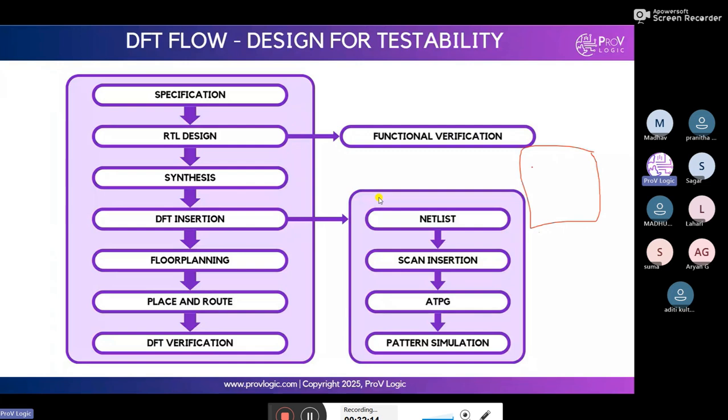In the system on chip design, it's a hardware part. In this SOC, we don't know whether it is working properly or not. There will be debugging issues, there will be some errors even in the post silicon. So we need to verify this hardware SOC. It contains a processor here and the memory here and some IO ports and some IO peripherals. To verify this, we insert the debug units. There will be some debug units, DBGSC modules will be there. The debug units will be inserted like this.